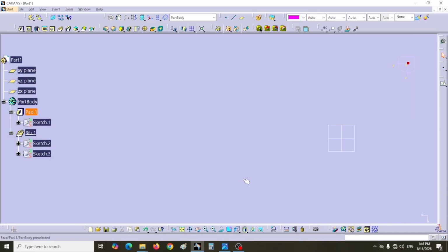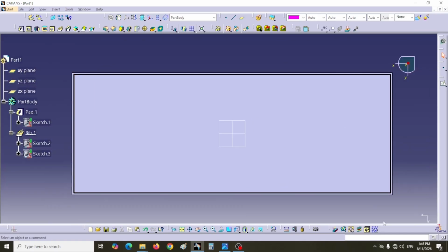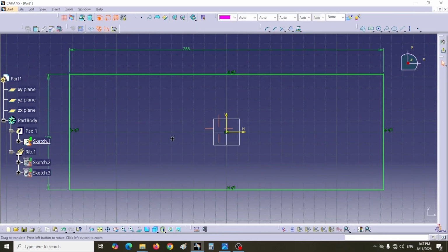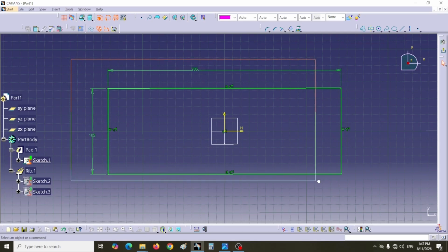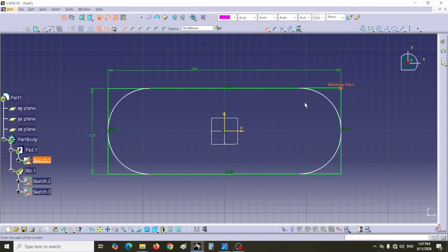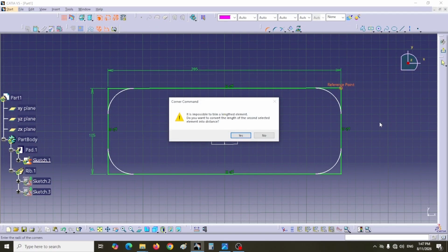I look at the shape from the top. Now the rectangle I created does not have fillets at the corners. I do not need to go back. I double-click the rectangle sketch. I enter its sketcher environment. I select the rectangle by creating a rectangular box around it. I activate the Fillet command. I move the mouse inside the rectangle. I click at a suitable point.